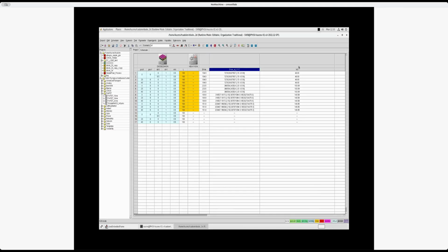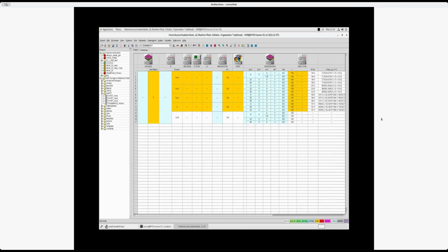And the last one, W0, is, for example, when we are depleting a diode, applying a certain bias voltage, and this extracts the depletion depth of your diode. This is nice, all done automatically. As you generate new cases here, all these values will be calculated as well, and you can look at the table and understand your simulation more easily.